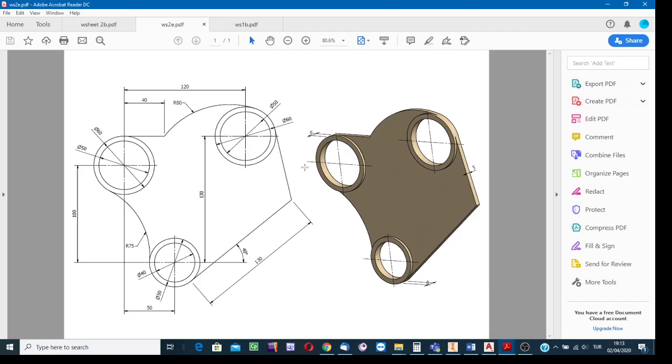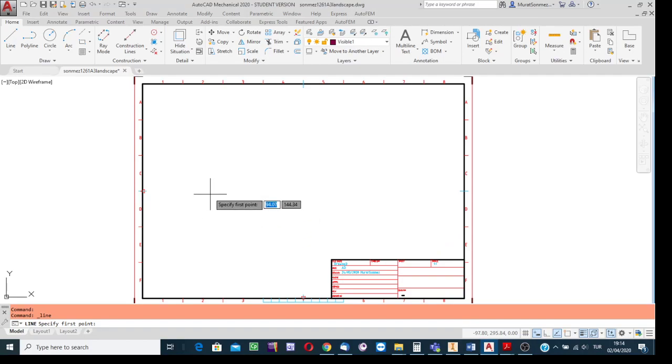So while drawing such a projection, it is said to select one of the points to start and then with an arbitrary click mark it on the paper. Indicate that location as the starting point. Most of the cases, yes, we do such a thing. But here in this example, say that the coordinates of the starting point are available. Say that the abscissa value is 100. After writing this number into the second box, press the comma key. And then into the next box, write the ordinate value. Say that the ordinate is 120.